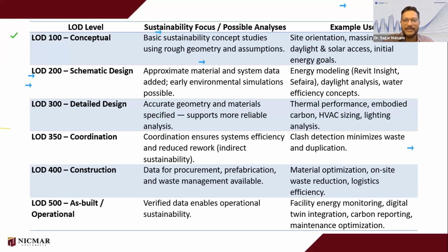But as you move to schematic design, it is expected that you are now doing energy modeling, more thorough daylight analysis, and taking into consideration water consumption, etc. And then as your model gets more mature and you start putting in more details, at LOD 300 detailed design, other concepts come into the picture, such as thermal performance, embodied carbon, HVAC optimization, lighting analysis, and electricity consumption.